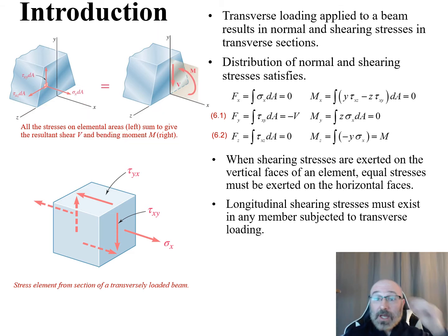By that relationship, knowing that we can sum all the individual stresses up to be the resultant shear and bending moments, we can use the distribution of the normal and shearing stresses to satisfy the following relationships.